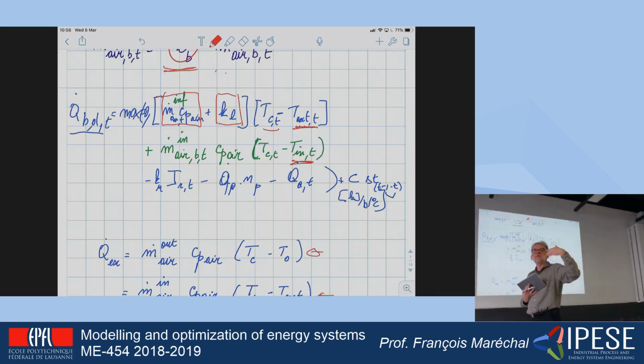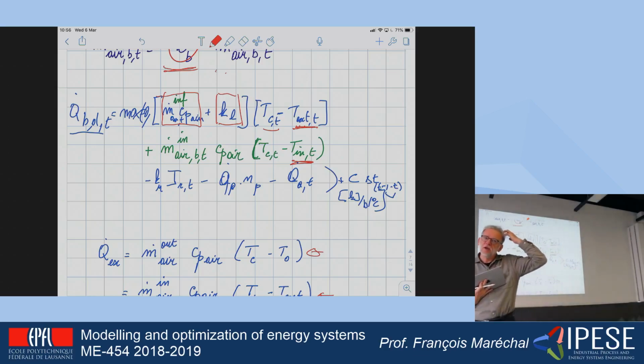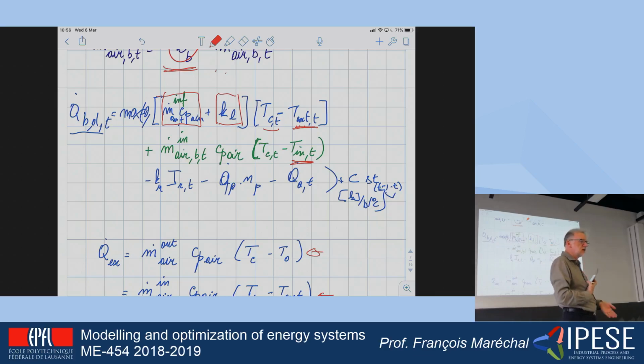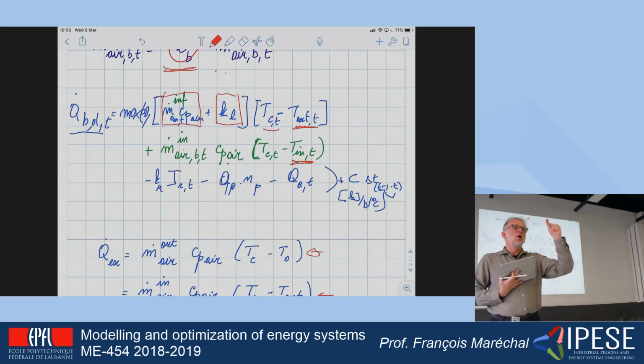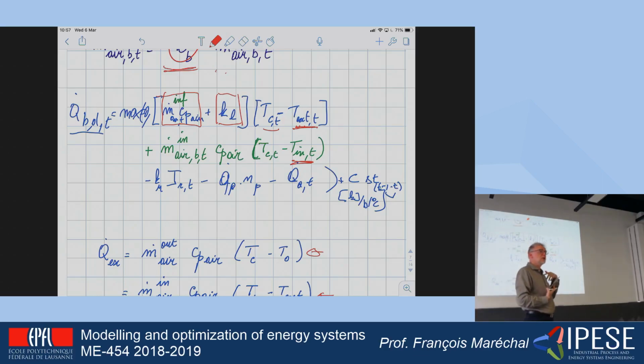And I have used another rule of thumb that says, okay, typically people consider that when the temperature is -10, for example, the temperature difference of the heat recovery heat exchanger will be 1 or 2. Okay, so a very limited amount of information is needed in order to assess different options to renew the building. Okay, and to make the calculation of the profile.